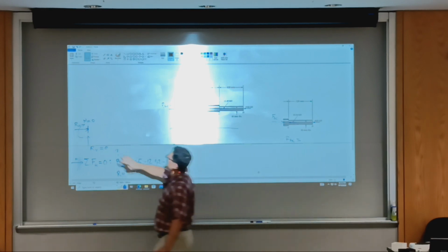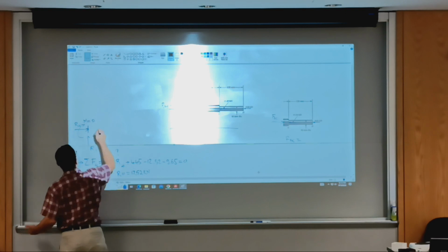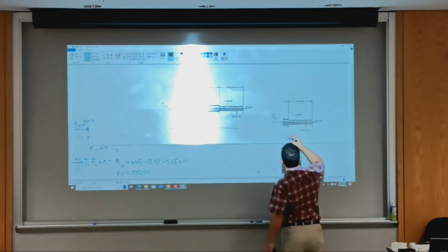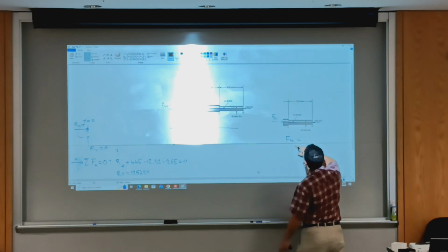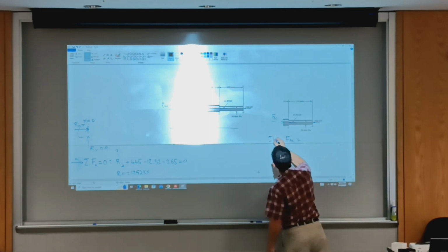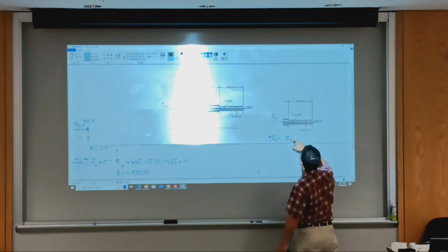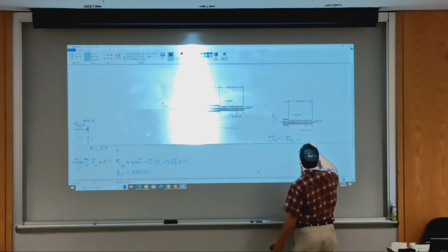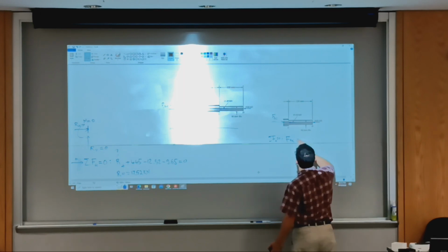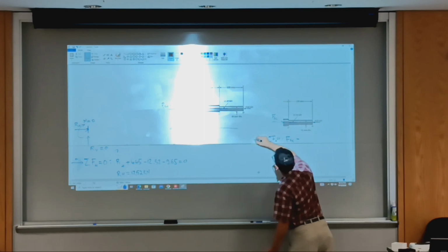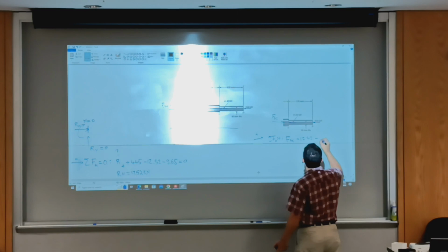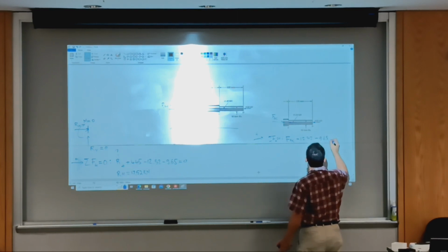So what is FBC? Essentially, we'll repeat the analysis that was here. I go back to the original drawing in place. So sum of forces in the horizontal direction equals 0, and we have FBC, assume positive, it may change, positive to the right, negative to the left, 12.32, and then negative 9.65 equals 0.